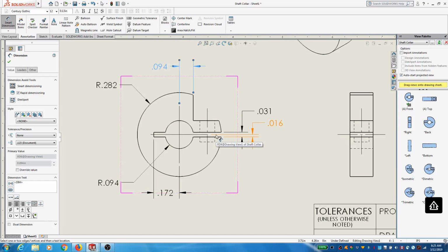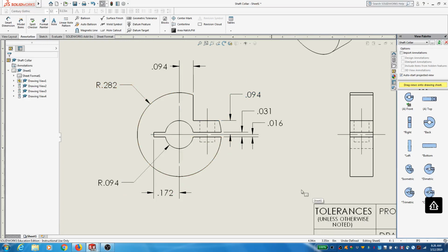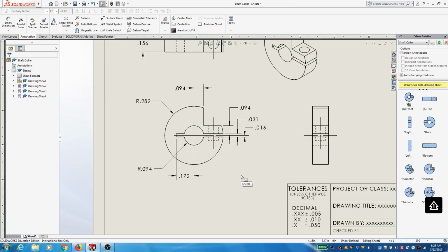On the original drawing that we used to create this, they came off of this bottom line, which I really didn't like. That was not good. So we're going to come off of this. Everything is measured off of the center of the part. That's how we're going to do it. Okay, so that specified this notch.